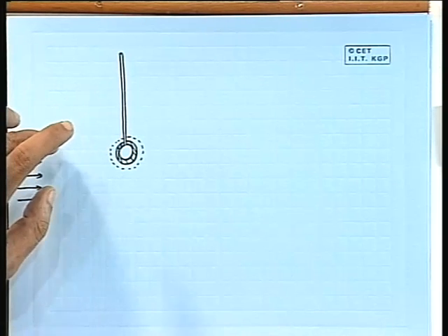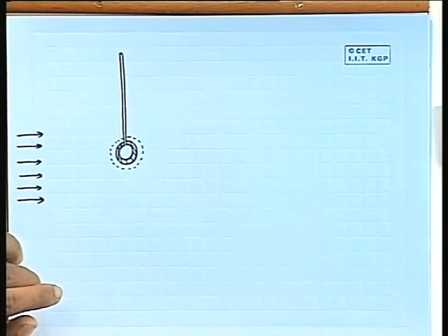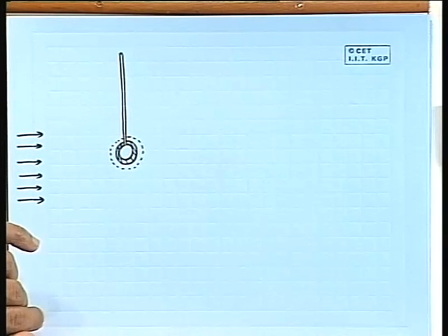So, there will be heat transfer from the air to the wick, and an equilibrium will be reached after a short while. That means energy transfer due to evaporation and energy transfer due to heat transfer will be equal, and then we will have a temperature indicated by the thermometer. That thermometer is the wet bulb, and that temperature is the wet bulb temperature.